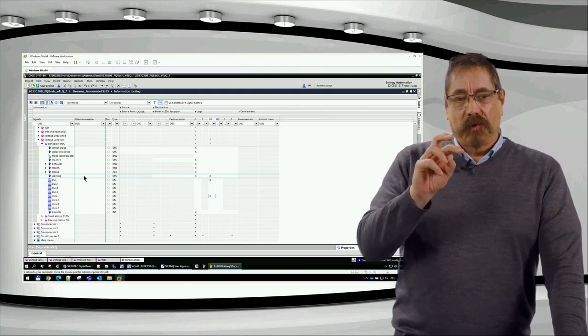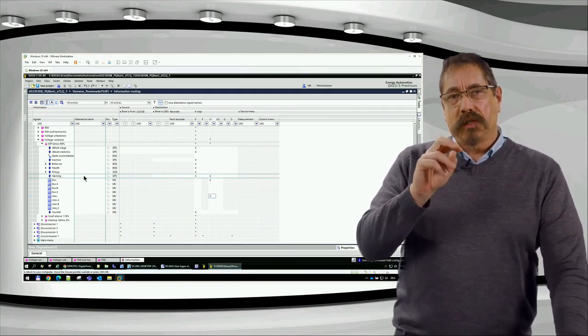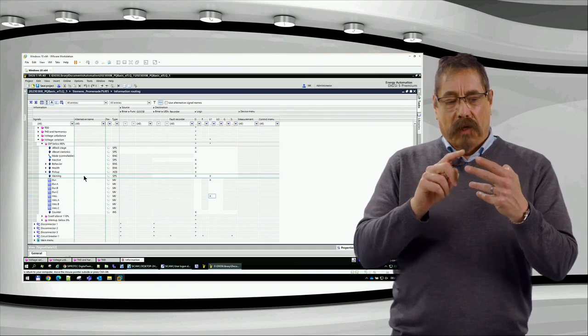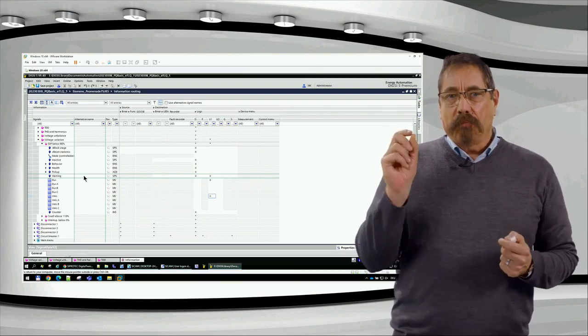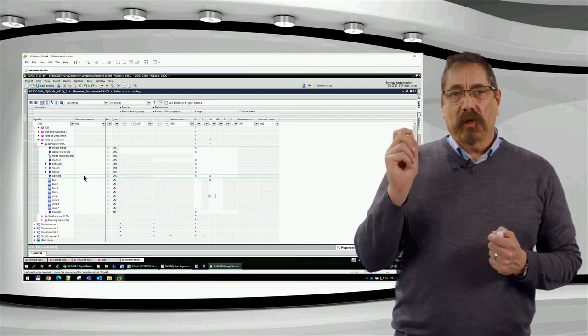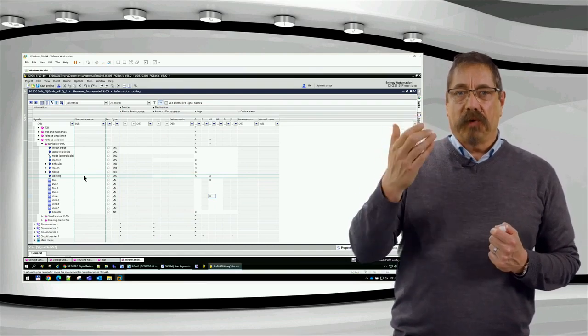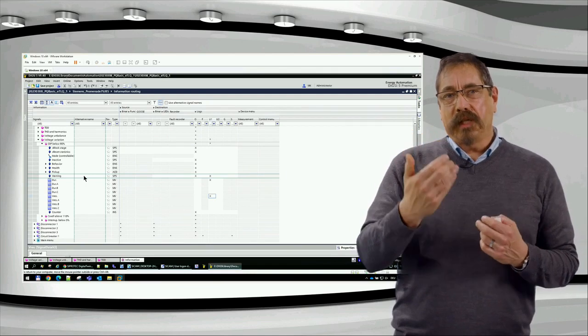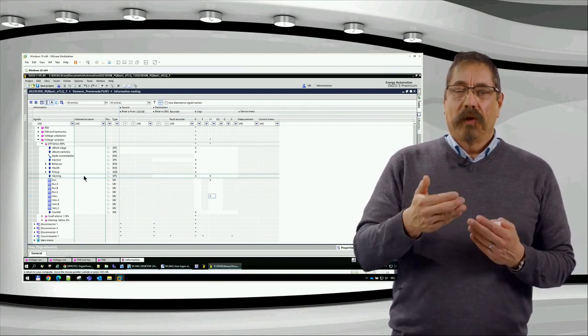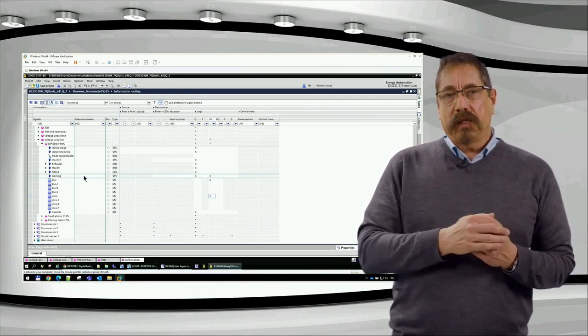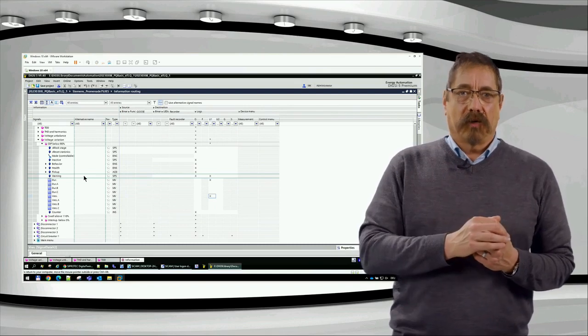Later on we will create the CFC logic with 3 inputs for dip, swell, and interruption warning, and the output of this OR logic will be an external trigger for the protection fault recorder. And when this complete file is generated, I need to know what was the trigger for this fault record, and therefore we will map these warning signals as binary tracks inside the COMTRADE.